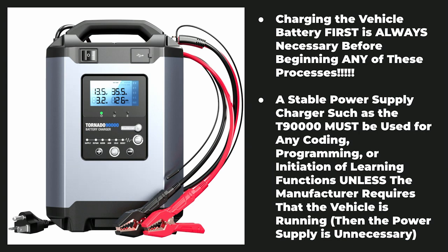Now, we want to make sure that we charge the battery on the vehicle before we undergo any programming or coding or learning. We want to test the battery with a load device. Now that could be with the engine, or we could be testing it using a carbon pile load tester. But we want to make sure that that battery is good and tests okay and healthy before we proceed with doing any coding, learning, or programming.